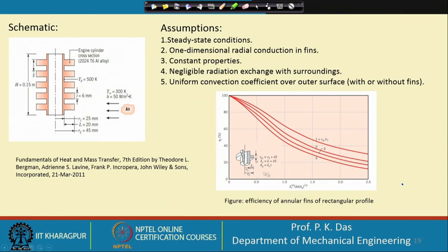Here you see the length of the fin has been written as Lc, and some correction can be done. If we neglect the heat transfer from the tip, we are taking an insulated tip, that is not correct. So, that is why the fin length can be corrected as has been mentioned here. This I have told earlier also.